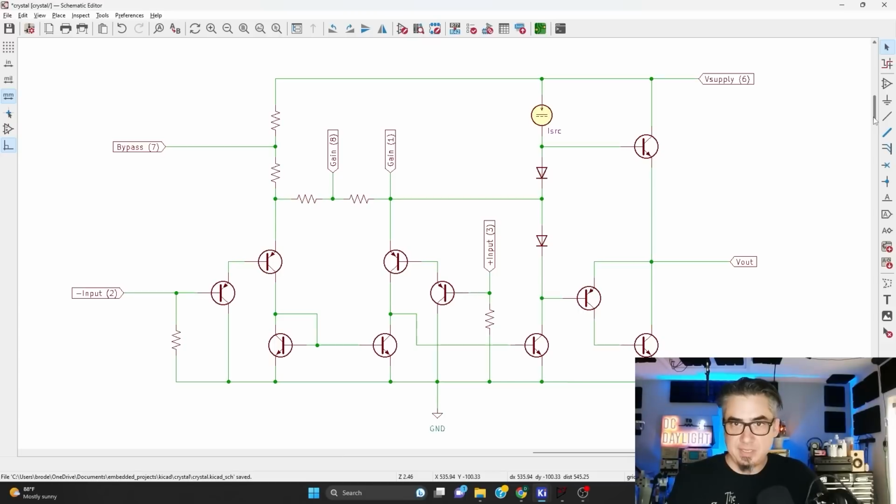So let's take a look at, this is a circuit for an LM386. And if you've been around electronics a while, you know that this is a fairly popular IC. It's been around forever. And we can use it as an audio amplifier. So it's kind of like a higher powered op amp. I mean, by high power, I mean like 100 milliwatts. And we can also connect a speaker directly to the output, which is pretty convenient. So let's look at the stages here and look at how we're going to use these bypass capacitors to do something. We're going to use them to increase the gain. So out of the box, without any external components, we can connect a power supply, input signal, and some stuff on the output in a speaker.